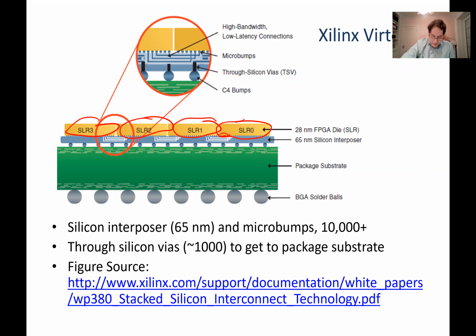So this is where the transistors and all the wiring, etc., is on the bottom of this chip. Okay, so it's been flipped upside down, and the last thing you put on a chip like this is what's called micro bumps. So little solder bumps, but they're smaller than the solder bumps you would normally put on a chip to mount it into a package. So that's why they're called micro bumps. The micro bumps are, I have to look at the exact technology, but on the order of say 50 microns, 30 microns. So much bigger than a wire, but significantly smaller than the regular bumps that you would use to connect to a package.